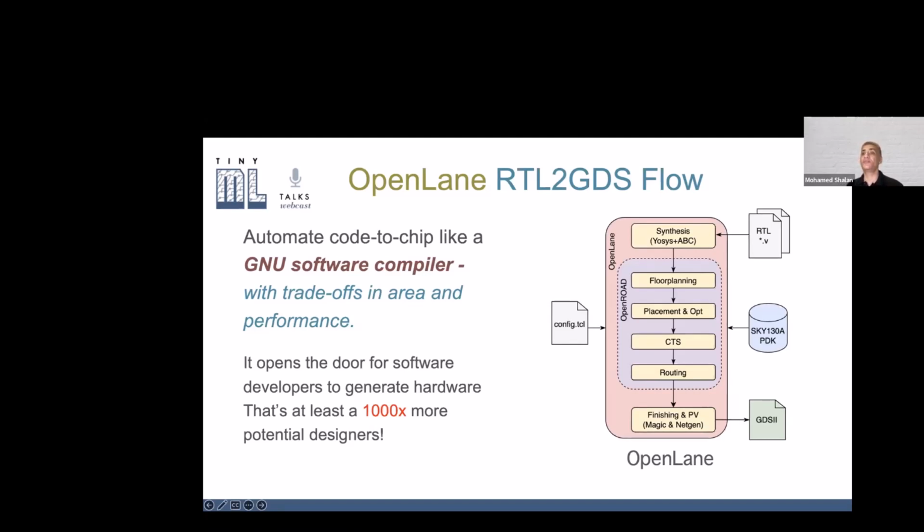These different steps are implemented either using open source EDA tools, in which case it uses the OpenROAD EDA toolchain, or if you elect for commercial EDA, we have a newer version of OpenLane, OpenLane 2, which has support for commercial EDA. And through our platform, you can use Synopsys EDA tools for your design if you want to do that.